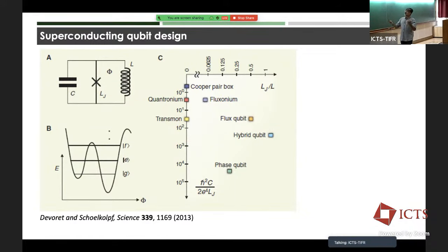I have not said anything about dephasing or decoherence at this point because I have not said how these quantities can change in time. The relaxation process comes when this object is not actually what you're implementing. The capacitor has some resistance across it because of dissipation in the dielectric. As we were saying, the Josephson junction could have a resistor across it because of quasi-particle transport.